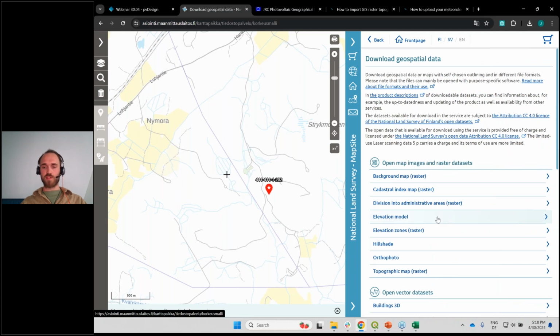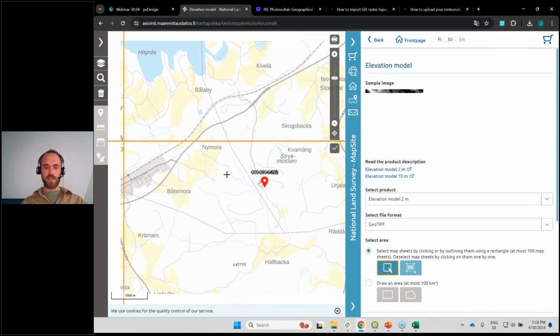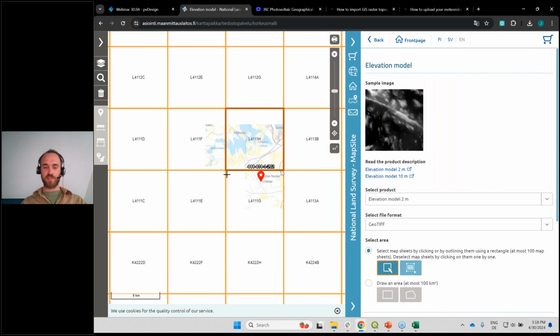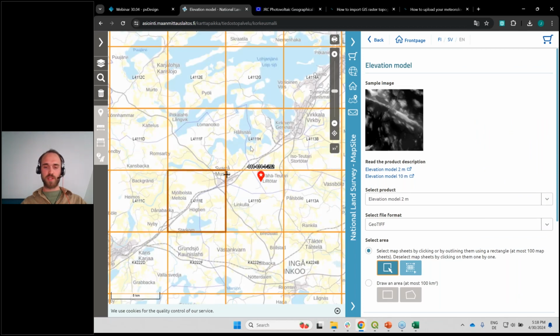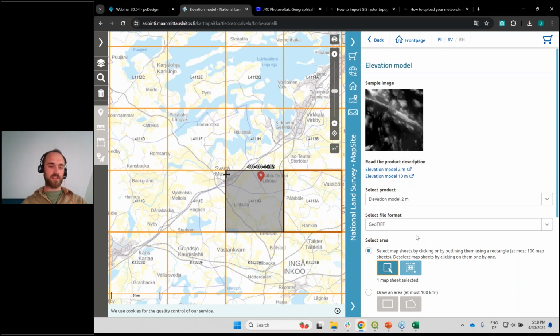And when I clicked on those, then basically I can see that the entire country is split into certain parcels here. So I just had to click on one of those and then downloaded the raster file. So the GeoTIFF file, I just downloaded it. It was available super quickly. And then with this information, I can now upload a far more defined, far more accurate topography file to my tool, to our RatedPower software.